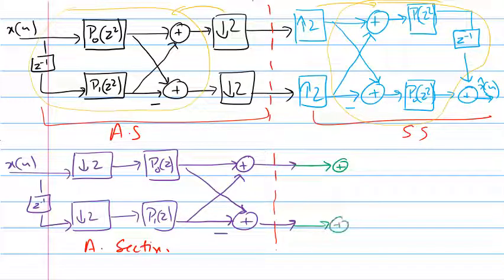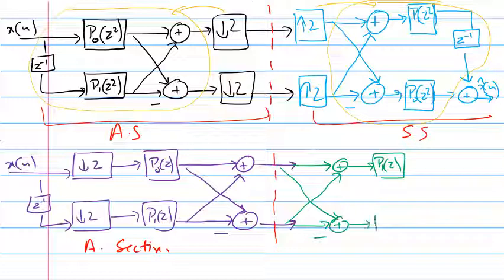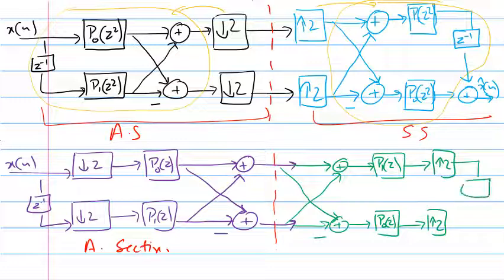Let's just move the negative sign here, and again apply a Noble identity over here. So this is P1(z) and this one is P0(z), then upsample by 2, then upsample by 2, then again a delay element like this. Okay, then add. So finally this is x̂[n].